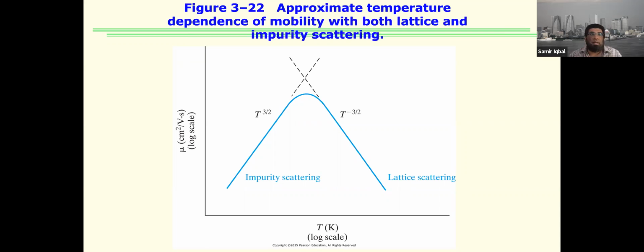So at lower temperature, the dominant effect on mobility, I want to use the word resistance to the movement of charged particle, but I cannot use resistance here because resistance is a very specific term. So that's why we say mobility is what helps us understand how easy it is for the carriers to flow. But it's a similar concept like resistance, but we cannot use the word resistance here. All right. So mobility is confined by the scattering between impurity particles by itself. But you ramp up the temperature, they start flowing much faster, mobility gets better, mobility gets higher. But if you keep on ramping, then the charge carriers start bouncing off the lattice itself. And lattice is composed of atoms in specific places, right? Crystal. So then mobility starts going down.